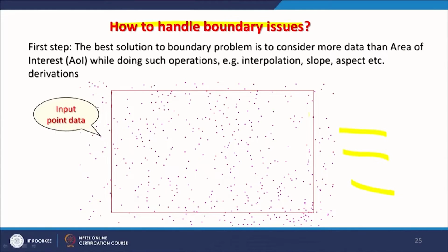So, that digital elevation model will not have any cell value created through extrapolation. All the cell values would be through interpolation, and this becomes very useful because the error would be very small. But if I take points only for my extent, like for this rectangle, then at many places, like here, there will be complete extrapolation. So, these areas will have errors because I do not have any observation beyond this boundary. So, it is always better, if that choice is possible, to do it.